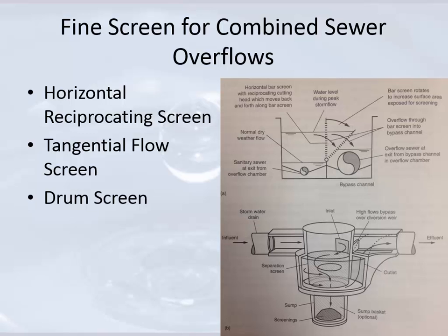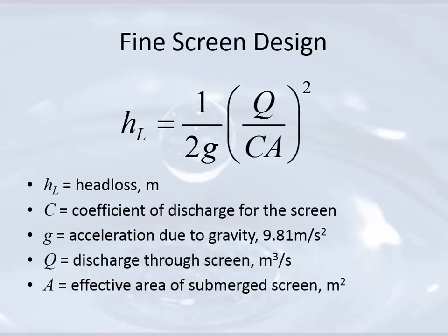And tangential flow screen has a chamber here, your wastewater flows through it, larger solids settle out. And your fine screen design equation here is pretty similar.